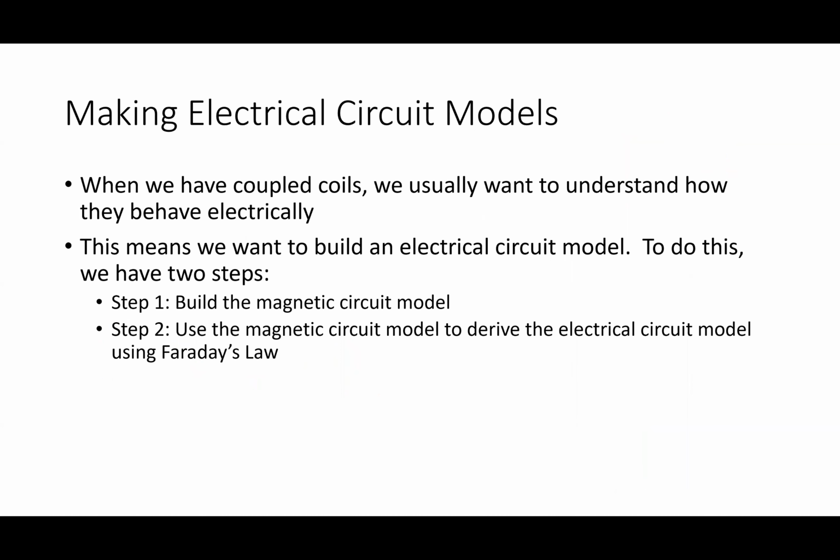Key thing, and this is what we do anytime we start looking at a device like a transformer, a motor, whatever: from the perspective of a user of the device, I don't really care about the magnetics. I care about what it does in an electrical circuit. So I want an electrical circuit model for a system with these coupled coils. To build an electric circuit model, I basically have two steps. I draw out the magnetic circuit model from the picture of the magnetic device,